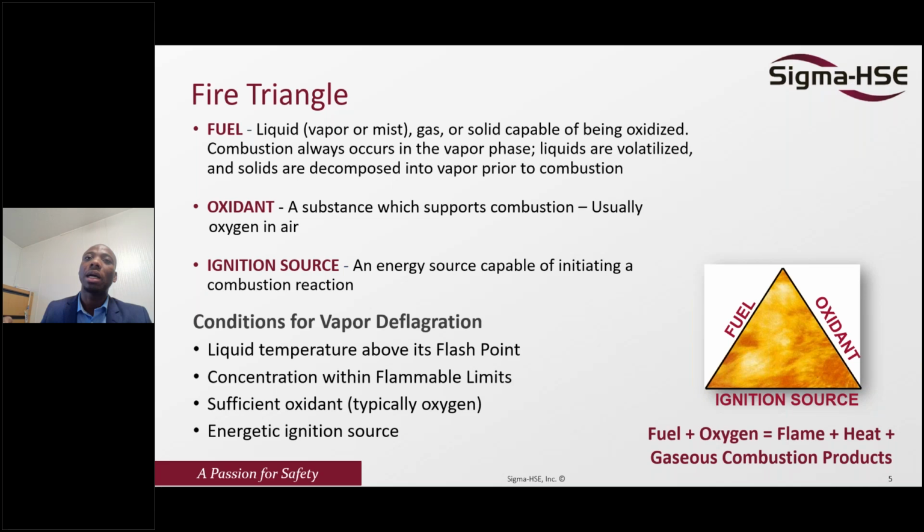And to have a vapor sufficient enough to sustain flame combustion is termed as a flash point. So we need to understand the flash point of this material. After knowing the flash point, we need to also know the concentration. I will dive into that very soon. We need to know the concentration, which is the lower and the upper flammability limit. We need to also know whether we have sufficient oxygen to sustain this combustion, and we need an initiator, which is the ignition source.